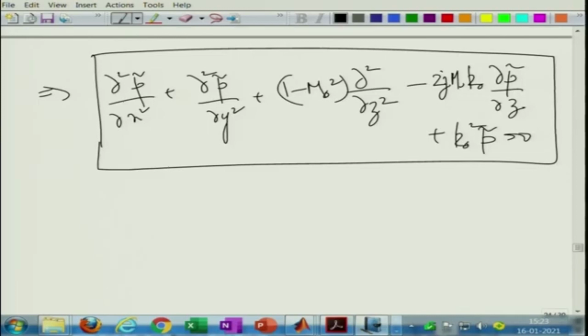So, the modal solution will involve terms which have M naught, or dependence on the Mach number, small Mach number, and for the more special case of M naught 0, we can get the case of a rectangular waveguide with 0 mean flow. Here of course we are considering a rigid wall waveguide. So, we will learn how to employ the rigid wall boundary conditions.